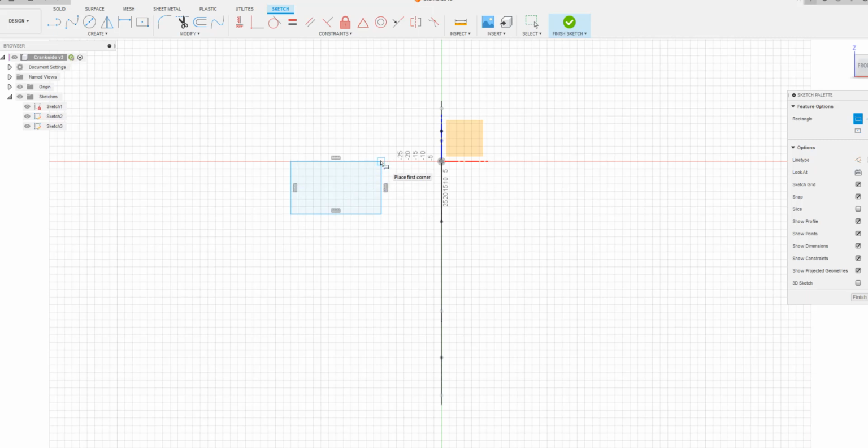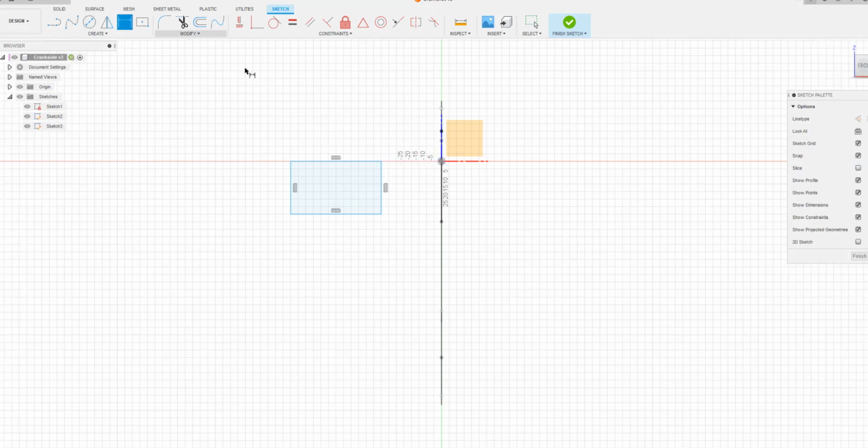The first dimension I want to add is what is the extent of this? What is this distance? So I can just take my dimensioning tool and I pick this distance here. And this distance is going to be not just a number. I'm going to add the side of the crank there, the side parameter. And I'm going to add to that the crank. I'm going to add to that the pin width divided by 2.